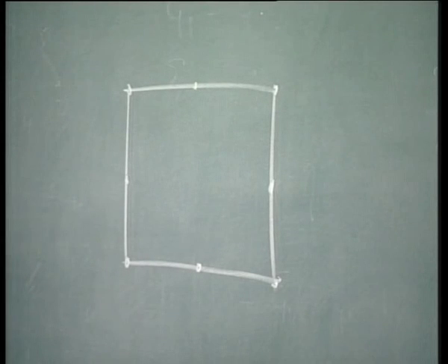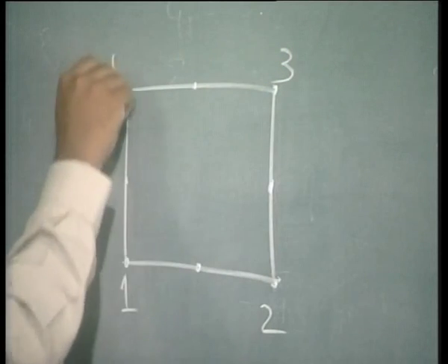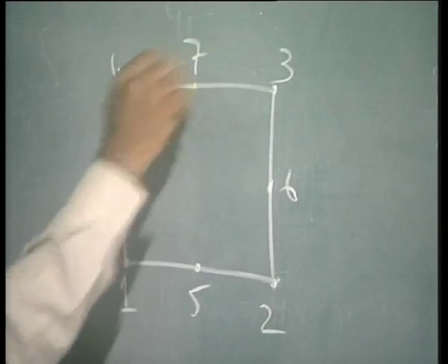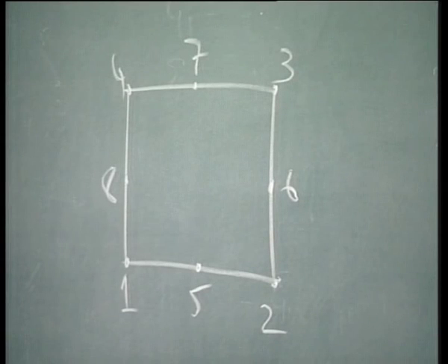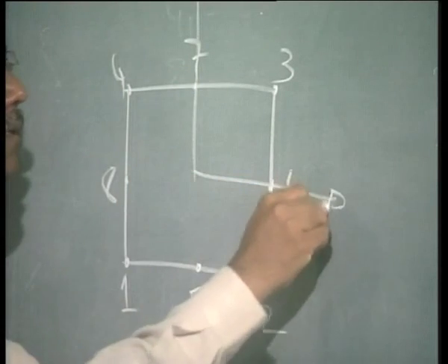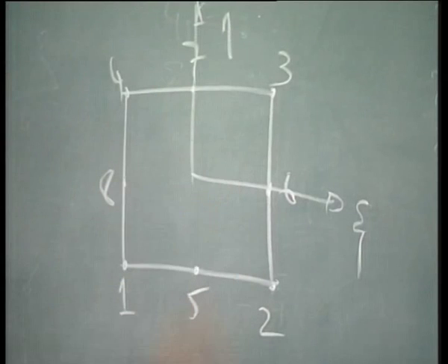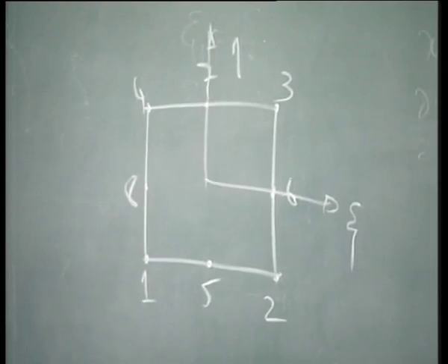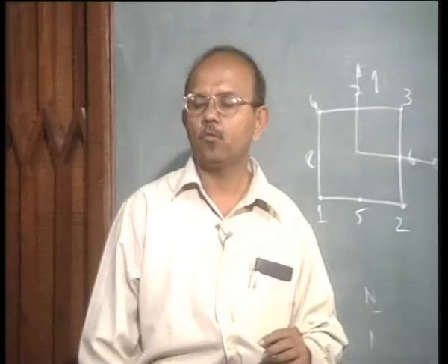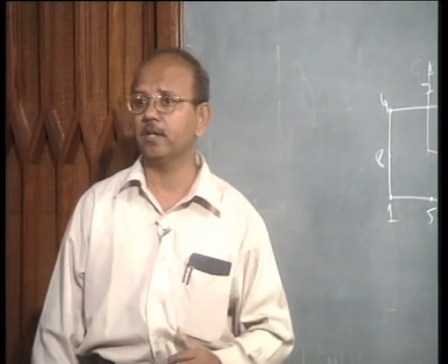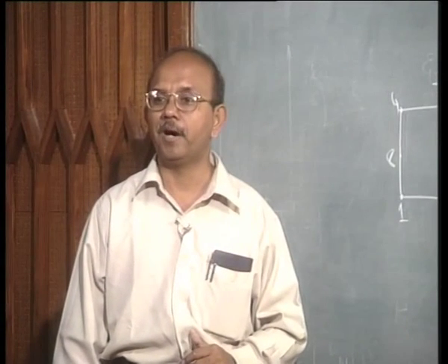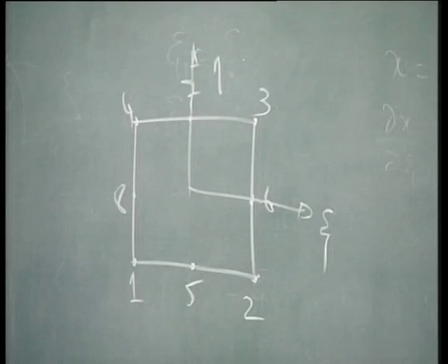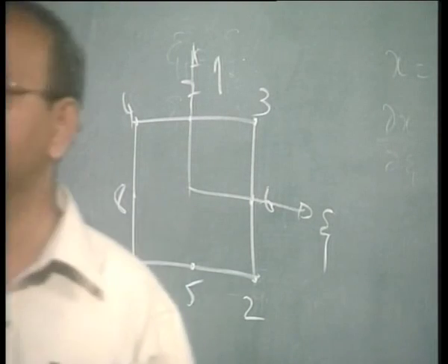Let's now look at 8-noded elements. 1, 2, 3, 4. Look at the numbering. It's always done like this. Psi eta coordinate system. Remember that we developed the shape functions for our 4-noded element by looking at the three methods which we did: inspection, then Lagrange interpolation.